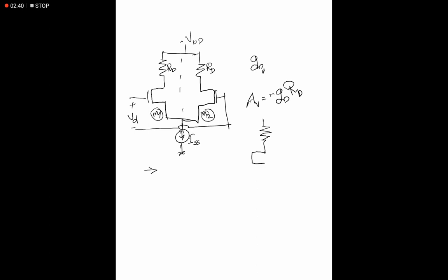If we consider the half symmetry in this circuit, here it is Vin1 and we are taking the output here, with VDD. This is nothing but a common source amplifier. I forgot to mark this one as N type, and here we will take the Vout between these two terminals. So this differential amplifier is nothing but a combination of common source amplifiers. The methods that we used to improve the gain of a common source amplifier are equally applicable to our differential amplifier, such as replacing this RD with a large value of resistance,